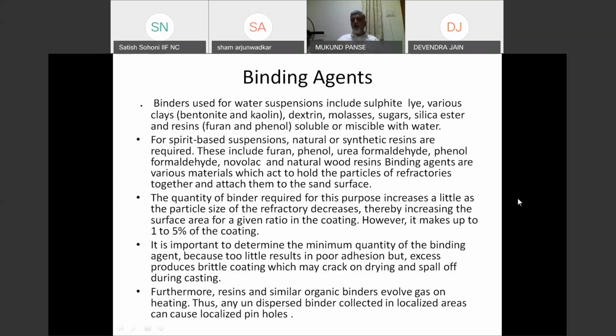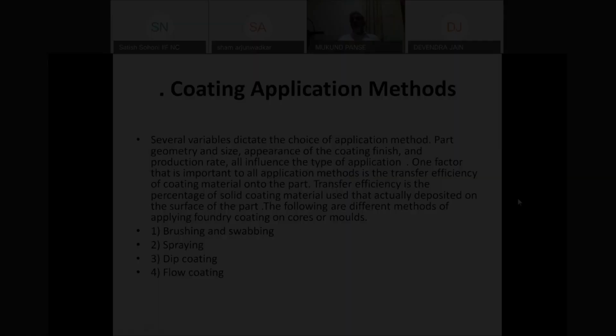So, for the mold sand system you are using, you have to settle on a proper mold coating which gives a uniform coating. You may have to carry out certain trials with different paints, but settle on a paint which gives you an exact uniform coat all over the mold. Furthermore, the binders themselves, when heated, should not evolve much gas because they are resin based.